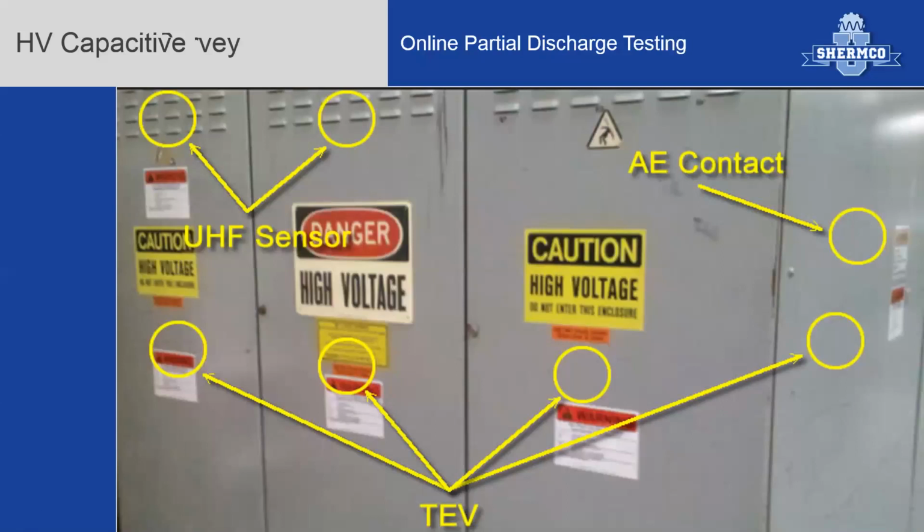Now again, if we're getting very high TEVs, but they seem to be over many panels, I may look for external sources of electromagnetic waves. I may look for space heaters in the area. I may look for variable frequency drives. I may look for fluorescent lighting fixtures directly overhead. That would basically explain why I'm picking up such a wide area of TEV.